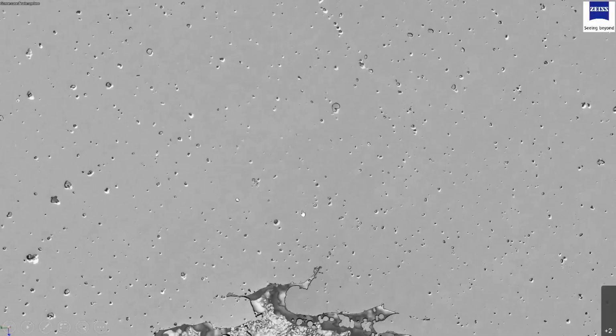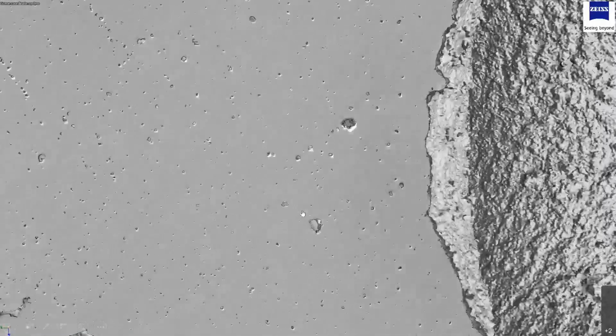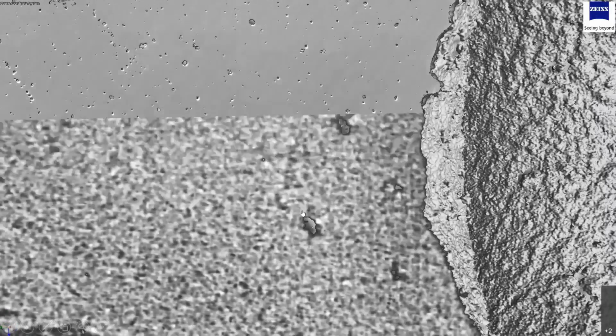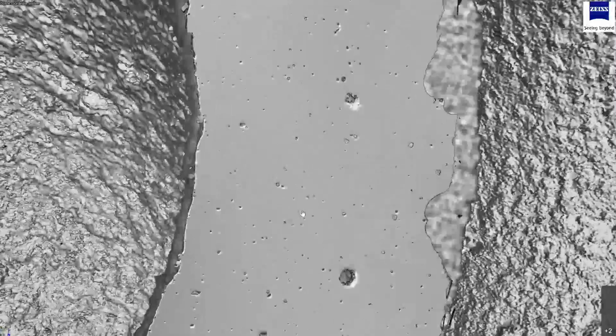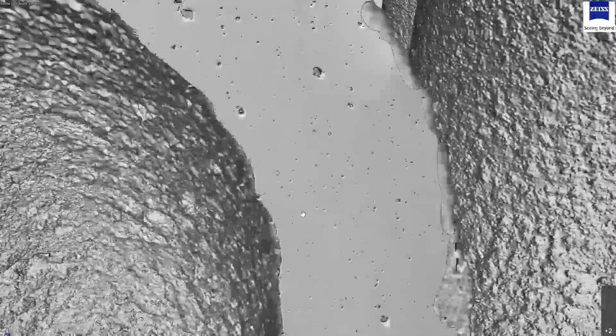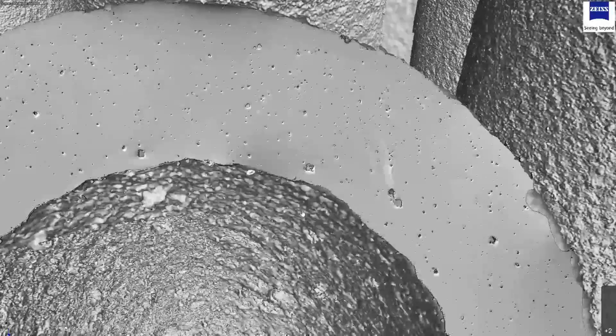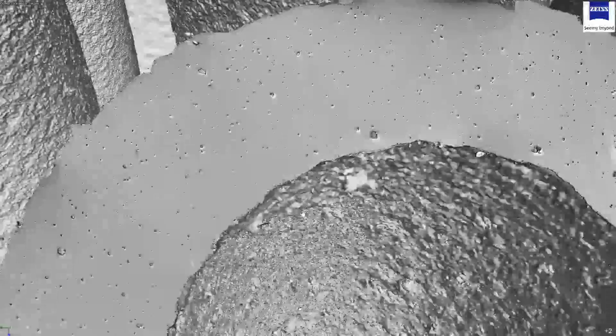And what we are able to do is not only show where the pores exist, but also go back and identify what caused the pores, if the pores are of a certain resolution. Because just doing CT alone is going to give you an answer, but that's not the final answer, because the coarser resolution CT, which allows you to see the entire part, might be too coarse to pick up small pores.